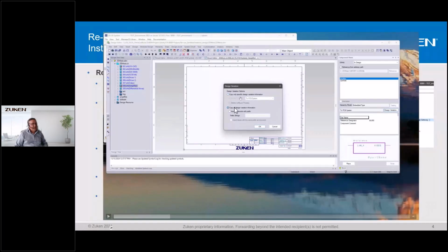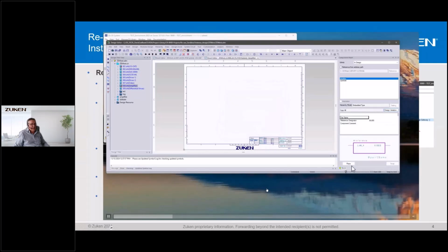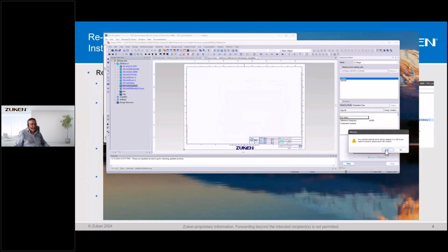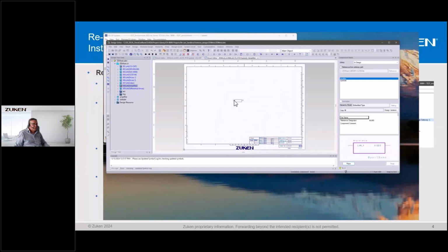You see you can select whether you want to keep just PCB variant information or copy all variant information, and then this is also inherited into my new design. So we place a hierarchical symbol. So we basically have the schematic now, but not yet connected to my design.